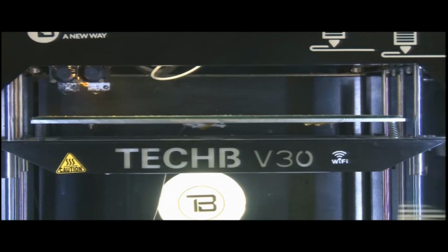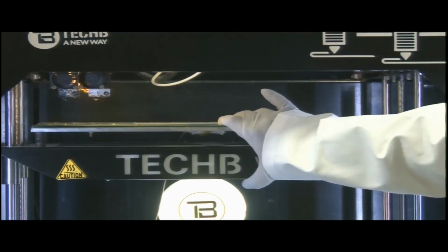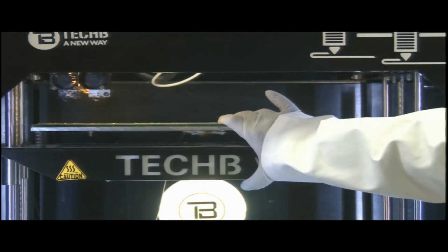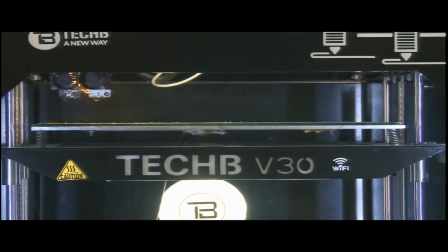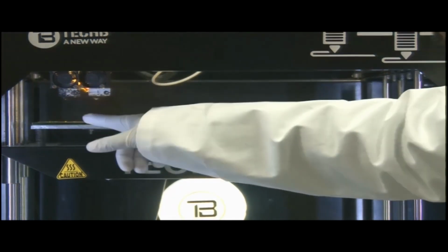When we fabricate a model of big size, the height increases, and sometimes it will vibrate due to the height, and the gap will vary. That is why the spring loaded mechanism helps to adjust the movement in the nozzle. You can see there is a spring mechanism here that helps to adjust the movement. In this way we make the leveling of the bed.